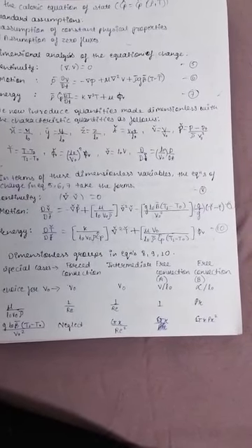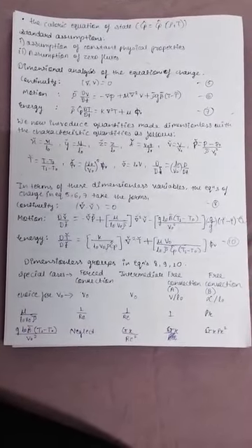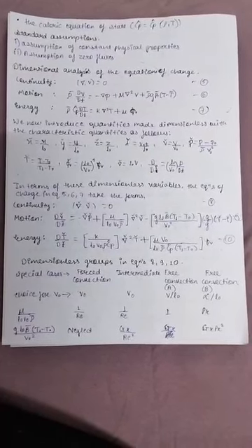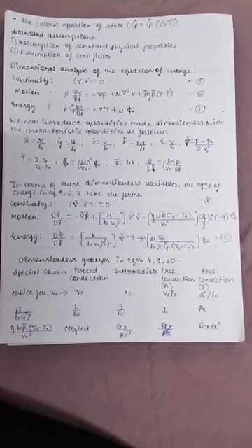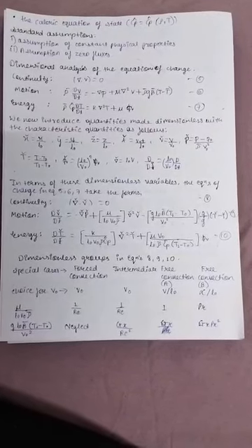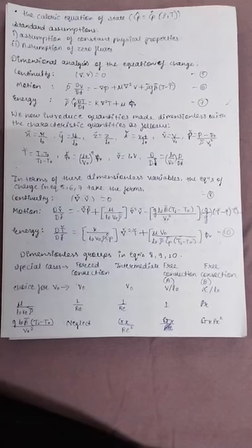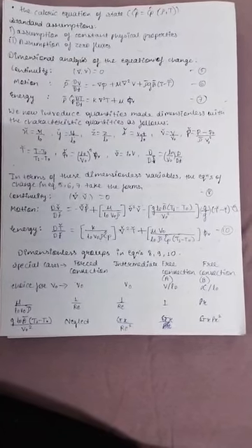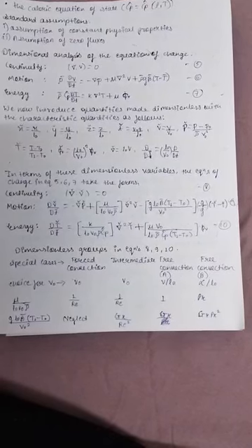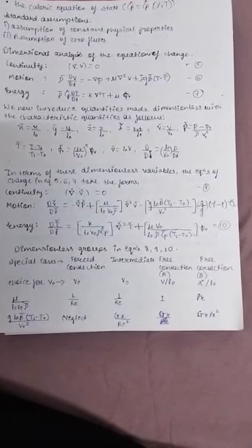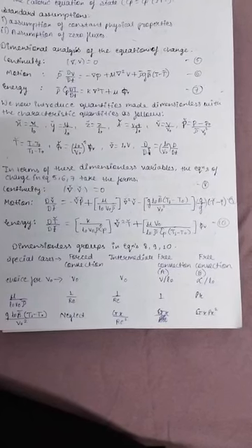We now introduce dimensionless quantities using characteristic quantities as follows: x̃ equals x over L0, ỹ equals y over L0, z̃ equals z over L0, t̃ equals v0 t over L0, ṽ equals v over v0, p̃ equals (p − p0) over ρv0², T̃ equals (T − T0) over (T1 − T0), Φ̃v equals L0 over v0² times Φv, ∇̃ equals L0 times ∇, and D/Dt̃ equals L0 over v0 times D/Dt.